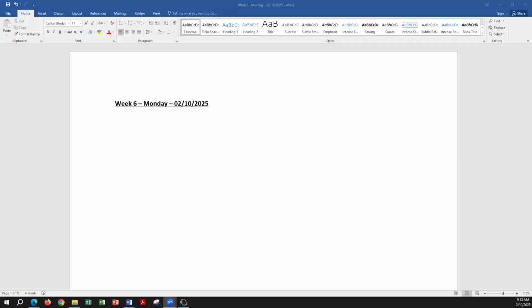Okay, so last week, Wednesday, we discussed the natural response of RC circuits. That is, if you have a bunch of resistors, one capacitor in the circuit, and you have a source that is energizing the capacitor. Once you remove the source, then how a capacitor is going to dissipate its energy through the resistors that are in the circuit. That's called the natural response of the circuit. And we saw that the capacitor dissipates its energy through an exponential function.